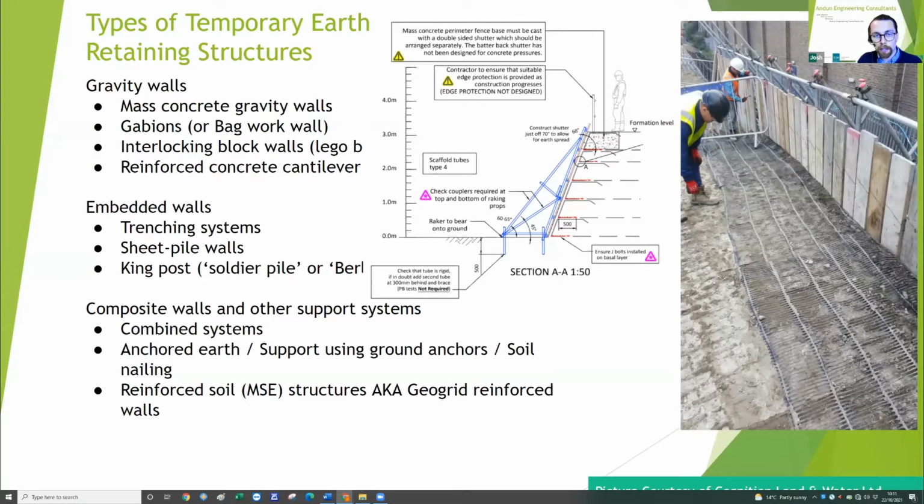The example shown in this picture is in Royal Wharf in London on the Thames. Here we utilised the reinforced earth structure to enable the project to be completed in 2 phases. The new area was about 3 meters higher than the existing level, so we created a steep embankment right along that phase line. The walls need to be constructed against some kind of former,